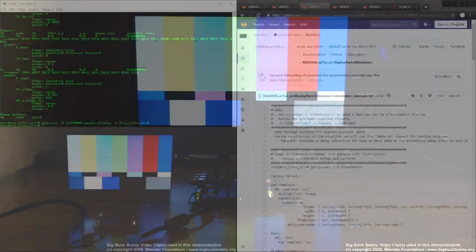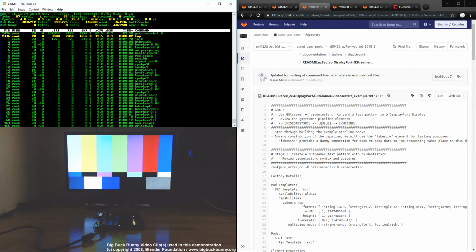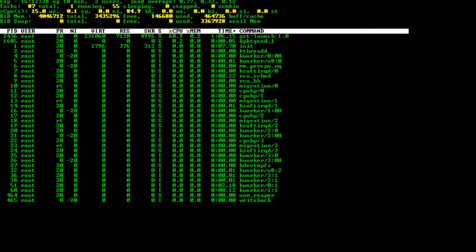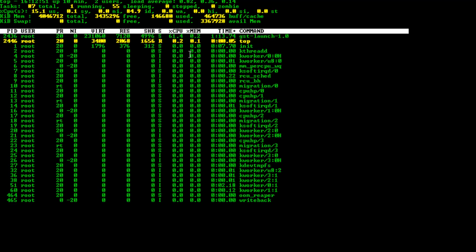So this is running 1920 by 1080. It looks pretty similar to the one we saw before because it's full screen. What's going to be a little bit different is the CPU utilization. Before we were generating a 720p test pattern, now we're generating a 1080p test pattern. And you'll see here that it jumped from 27% to 61% of a CPU. That's just one of the CPU cores, one of the Cortex-A cores that's generating this test pattern at 15 frames a second, 1080p.